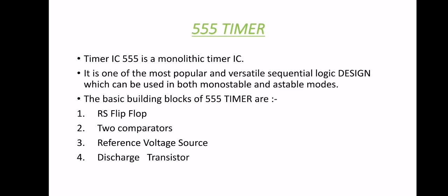What is 555 timer? As I've written, 555 timer is a monolithic timer integrated circuit. Integrated circuit or monolithic integrated circuit, you can call them either one, is a set of electronic circuits on one small flat piece of semiconductor material that is normally silicon. It is one of the most popular and versatile sequential logic designs which can be used in both monostable and astable modes. The basic building blocks of 555 timer are RS flip-flop, two comparators, reference voltage source and discharge transistor.